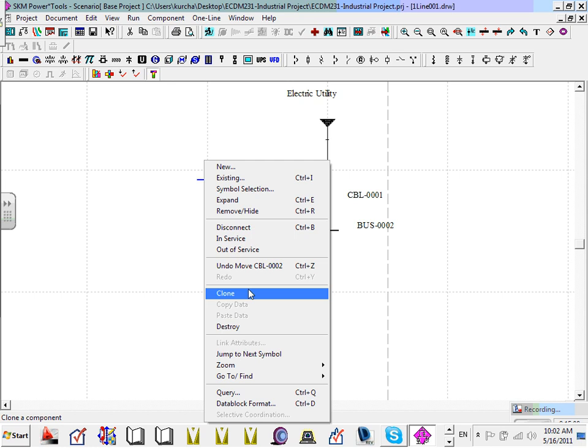So Brad, if you did one project very similar to another, where one section is identical to the other section, you do the same section, you're done. Clone it. It will make an identical copy with the database with it, and you move it to the side and you connect them, done. Cloning is like copying, guys, but more powerful than copy because it clones the picture as well as the database.